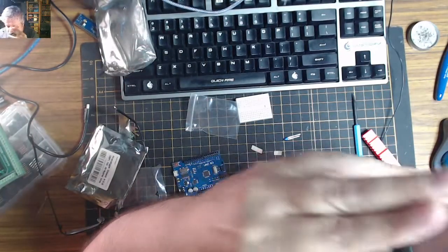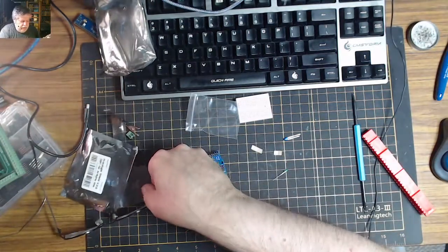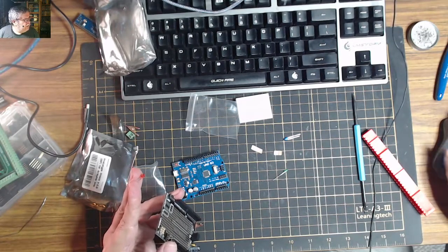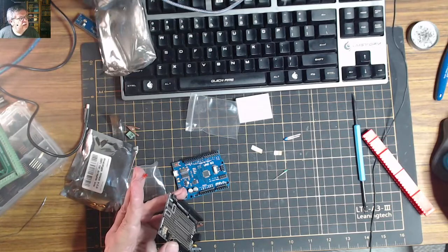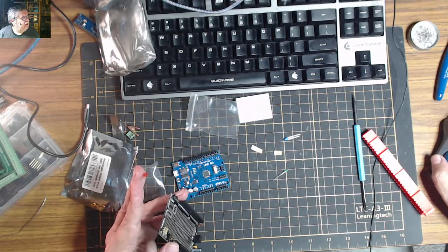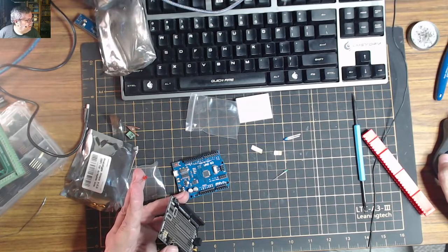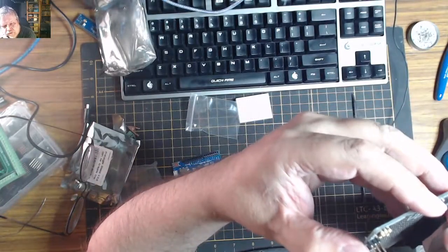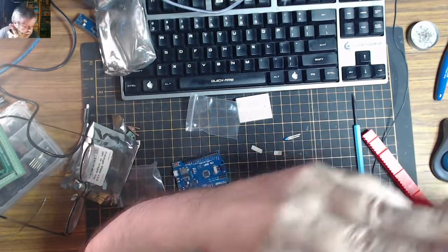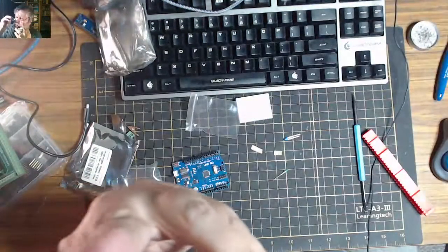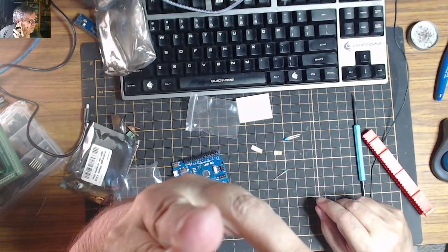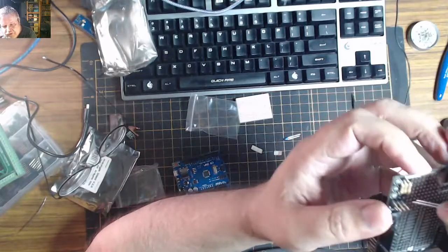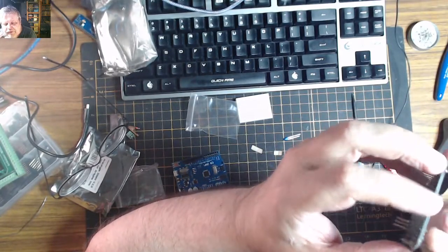And of course, I'm notorious for this. Every time. You think I can remember how to spell Mississippi? Yep. Can I remember the polarity of an LED? Nope. LED polarity. Long leg is plus. Okay, so long leg is plus. And then these guys don't mark it plus. They mark it with triangle and slide. So triangle is the plus side. Meaning right here goes like this.